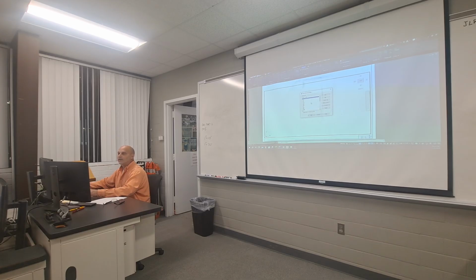To add those additional scales, you've got an add button up here on the top right. You can see right below it, you've got an edit button in case you mess something up. I'm gonna pick the add button, which opens up my add scale dialog box. I'm gonna type in the name, just like your other scales. You want it to read what you're gonna put in your title block. 3/8 of an inch equals 1 foot dash 0 inches. 1 inch equals 1 foot dash 0 inches.